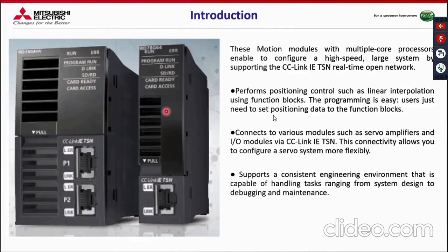Whenever you do programming with this motion model, there are some options. You can use buffer memory, you can write programs in ST language, or you can write functional blocks. But the main positive thing is that this model has built-in functional blocks available with it. It connects to various modules such as servo amplifiers and input/output modules via CC Link IE TSN. This connectivity allows you to configure a servo system more flexibly. Because of that, we use the RD78G4 model.